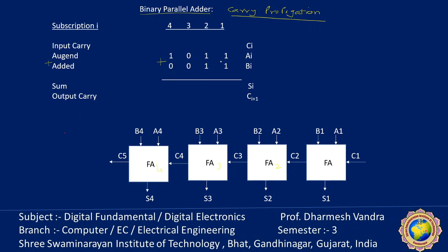Here A and B are available at the initial stage for the computation at the same time. As in any combinational circuit, the signal must propagate through the gates. Suppose I input these two, they go through the full adder circuit, and it generates the output. The total propagation time is equal to the propagation delay of a typical gate times the number of gates in the circuit.